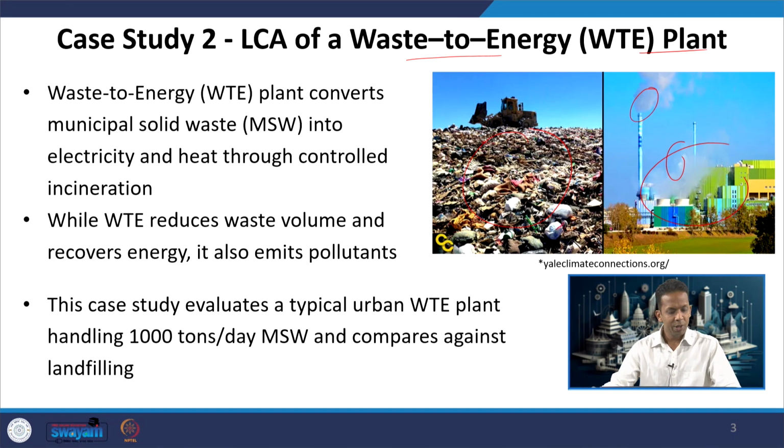A waste to energy plant converts municipal solid waste into electricity and heat through controlled incineration. This does not mean that all waste to energy plants are based on incineration only. In India, you would have some plants based on gasification, pyrolysis or even anaerobic digestion. If it is just food waste or animal waste, anaerobic digestion is a very good process to generate methane, and it also comes under the category of waste to energy.